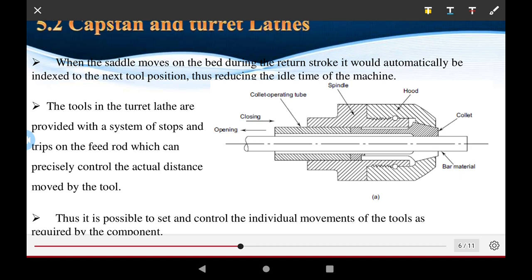A value is given for the x direction, and the tool is moved in the x direction. Given the x value is 4, cut for the feed rate, select the feed rate and the length. The x value is 5, and the machine turns to start the operation. It cuts the material in the x direction for the given x value of 5, that is, 5 mm.